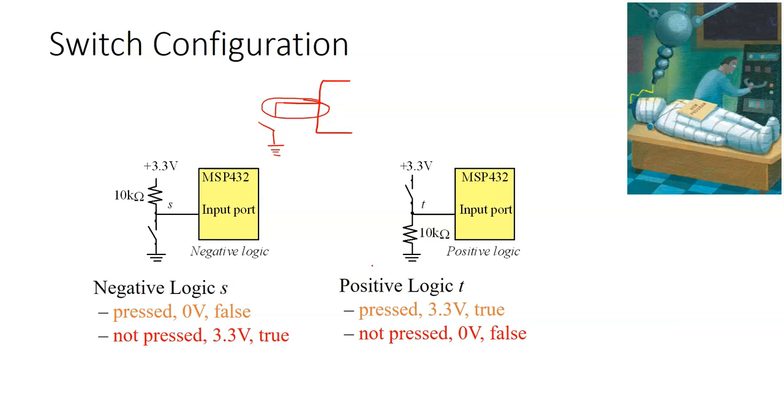Remember, our CMOS logic is built to be robust. It can tolerate some noise in the signals. But in this case, it's not clear, depending on the temperature, the noise, and the circuit, what voltage the net is going to go to. And worse, having floating pins could consume a lot of power. And even worse than that, this leaves the circuit susceptible to electrostatic discharge, which can permanently damage the devices.